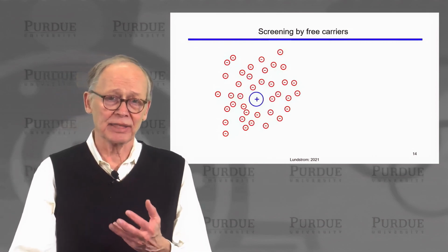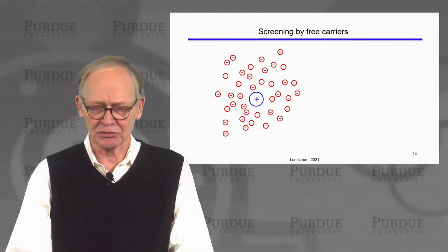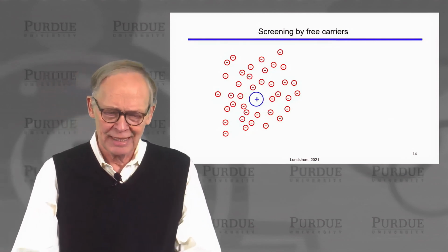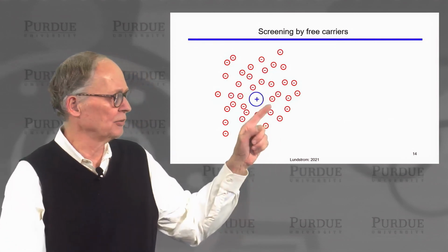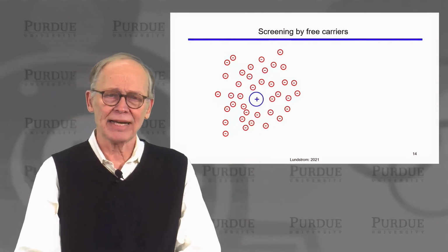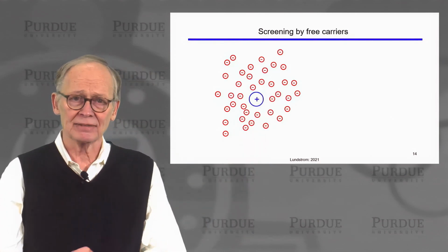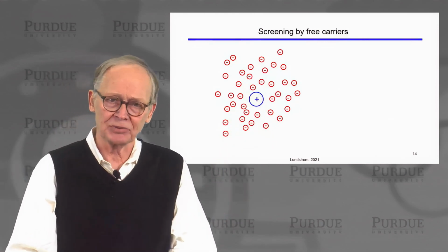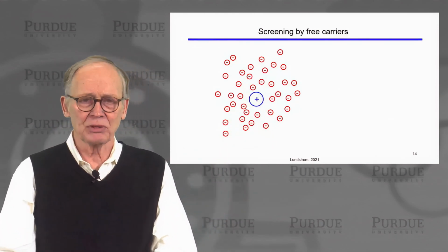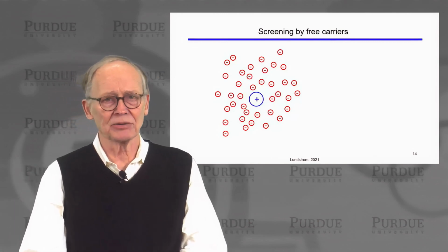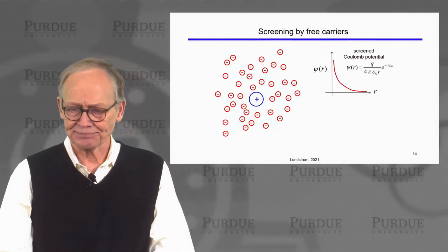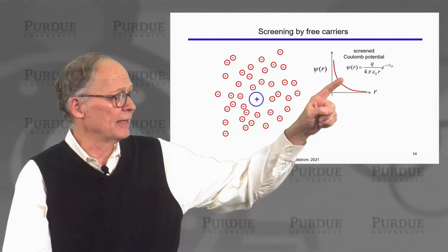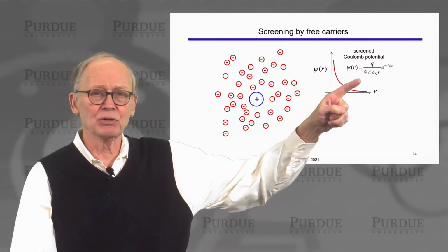The concept of screening is important for this discussion. And I'll just remind you, if we think about a bulk semiconductor, not a small MOSFET, but a bulk semiconductor where we've doped it N-type, we have ionized donors, they'll be positively charged. They will attract the mobile electrons that are in the N-type semiconductor, and those negative charges will screen out or cancel the positive charge.